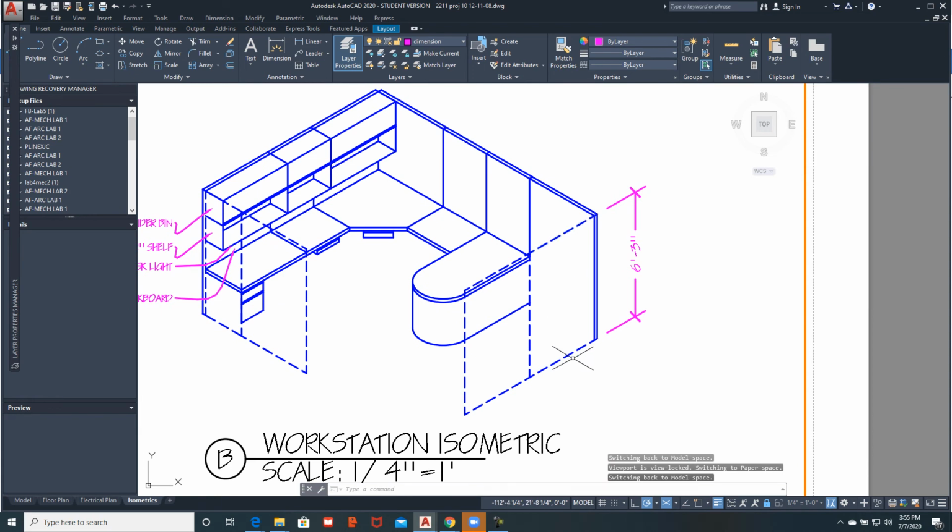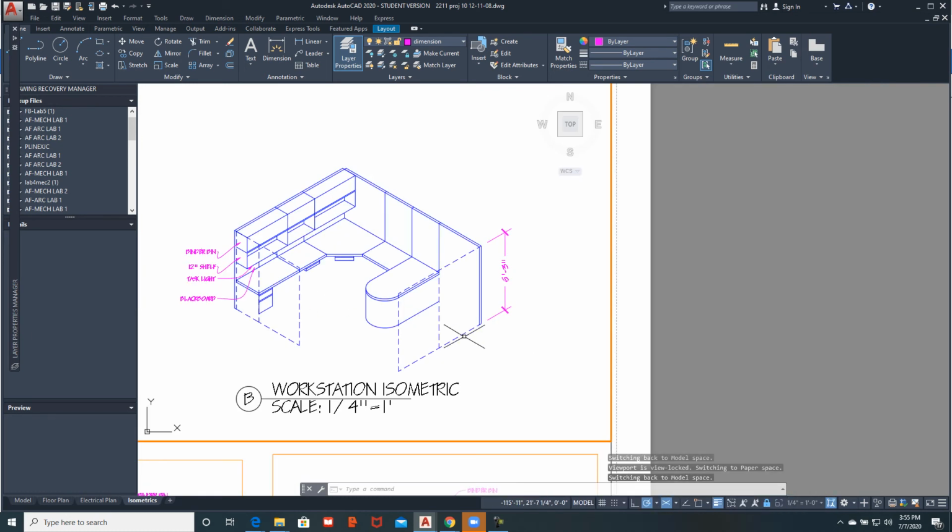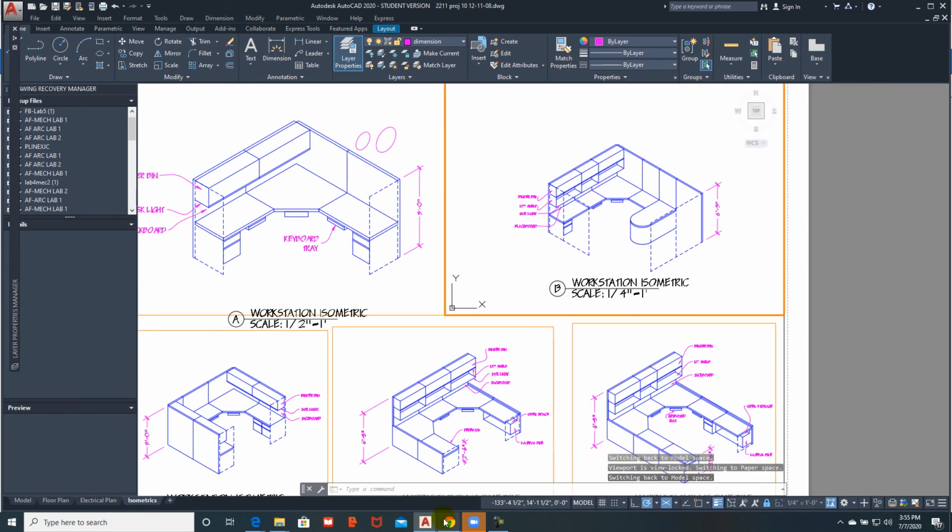And so you can see it has these hidden lines for these office wall partitions. Now if I go and I change the LT scale by typing in LT scale, and I change it from 0.5 to let's say 10, now it looks like those lines are no longer hidden. LT scale, and I'll say 0.5. And so it allows you to adjust the scaling or the space between the dashes. And the way that you do that by the book is it's the inverse of the plot scale. And we'll talk about that at another time.